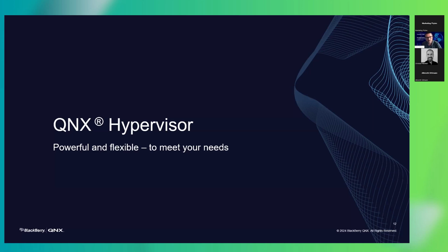Now, the power of compute platforms has increased in the embedded domain. Designers have the luxury to add more functions on each SoC. These functions can be different and combine safety-critical and non-safety-critical processes. The challenge is to isolate these functional domains such that they do not impact each other negatively. And for this, we have a powerful yet flexible hypervisor.